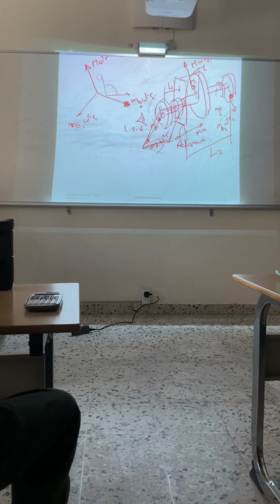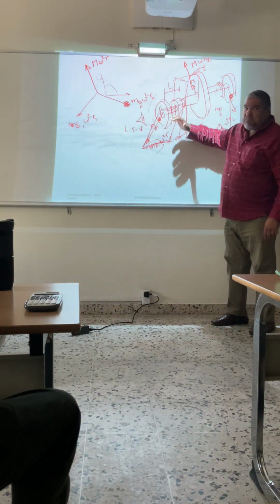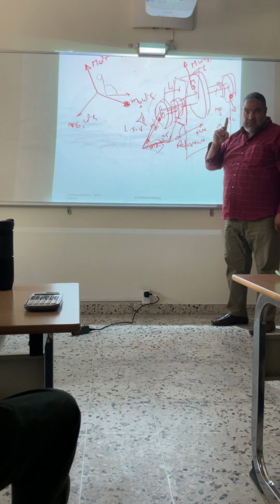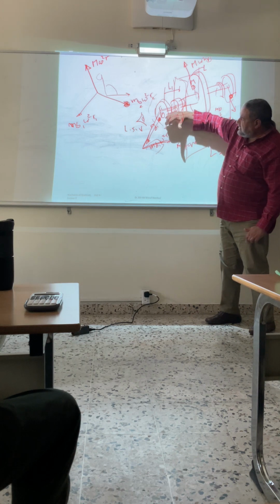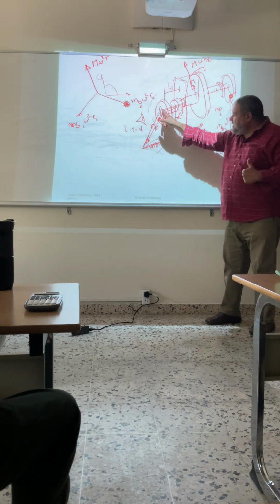Okay. Now guys, based on the right-hand rule, if you need to figure out the direction of the moment, we usually let the fingers rotate with the direction of the force. Imagine, guys, that I'm facing the board right now. Okay, I have to do it here. Here is your force. And now I'm going to let my four fingers rotate in the plane of the force. Clear? Yes. If you let your fingers rotate in the plane of the force, this means that your thumb is perpendicular to what? To the plane. Perpendicular to that plane, right?